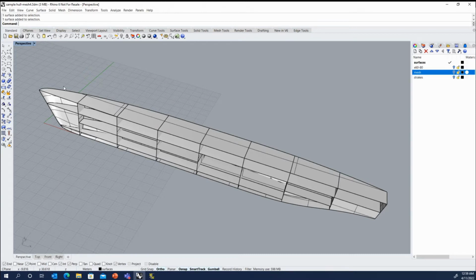It might be significantly longer up at the bow, so that if you have a standard stiffener spacing, let's say you only have 5 stiffeners at midships here, you might have 8 or 9 up at the bow. So those need to appear at some point along the hull here. So we don't necessarily want just flat planar cuts through there. You might want an even girth along the length. And that's what one of these scripts will do.